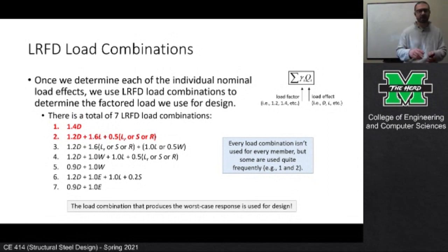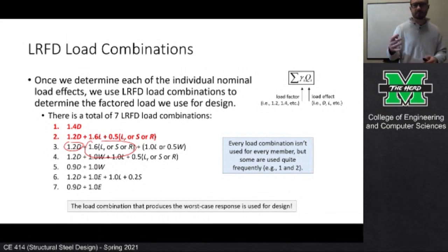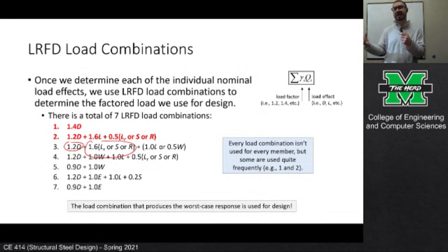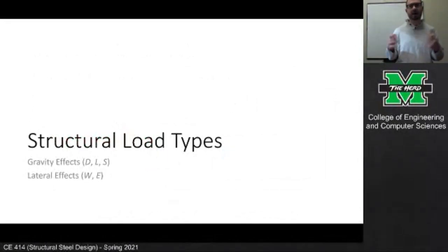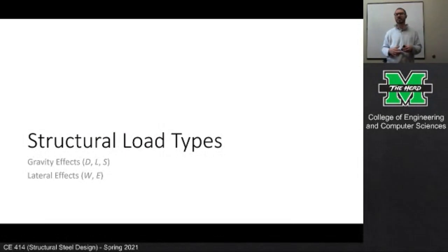If you look at load combination 3, what it's saying is you've got 1.2 dead, and then 1.6 times essentially whatever the maximum effect on the roof is. It's either the live load on the roof, which would be construction or maintenance or workers or whatnot, snow, or rain. The one that's critical and tough to understand is the snow load, so that's why I'm moving past that. And 99 times out of 100 it ends up being what governs anyways.